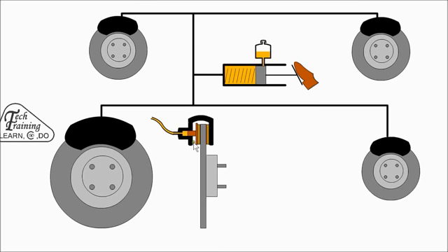When the brakes are applied, the rubber seal deflects slightly. When the brake is released, the seal returns to its normal shape and moves the piston back slightly from the wheel. If the fluid expands due to heat, some can return to the reservoir. If there is a leak in the system, the fluid will be topped up from the reservoir. Excessive leakage will be detected by the level switch. If there was a severe leak in the system, we would lose all brakes.